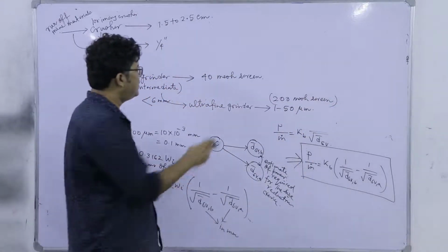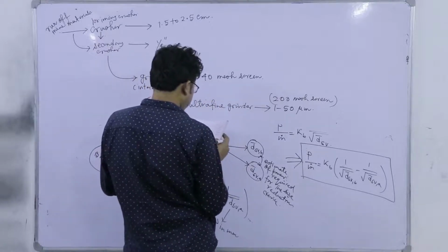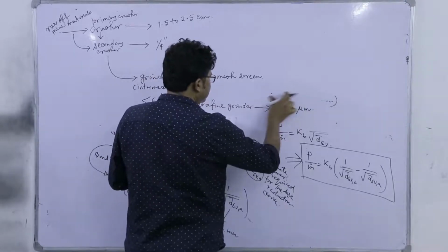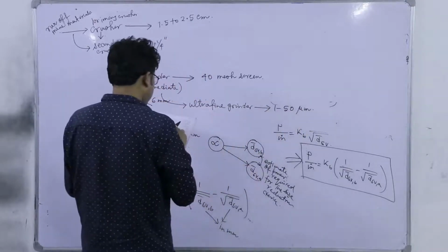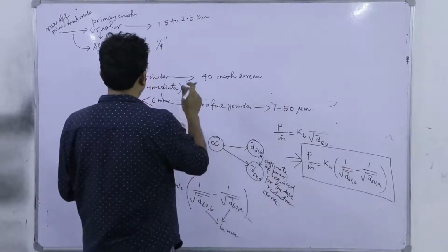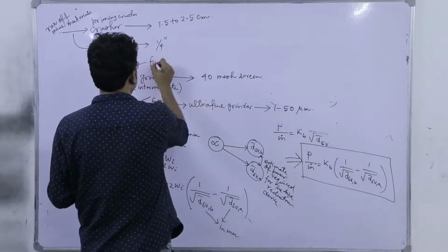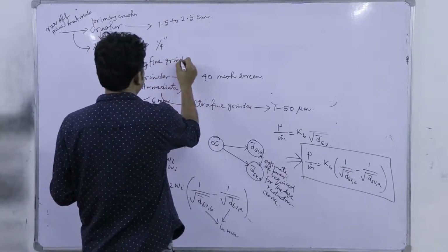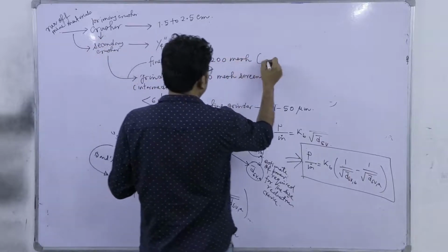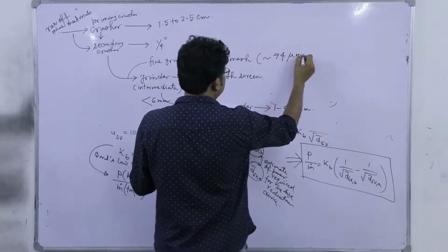And this 40 micron screen size, no, this one is not 200 mesh. The fine grinder's product passes to a 40 mesh, this is the intermediate. Then if you feed it to the fine grinder, it will be producing 200 mesh, which is around 74 micron, right.